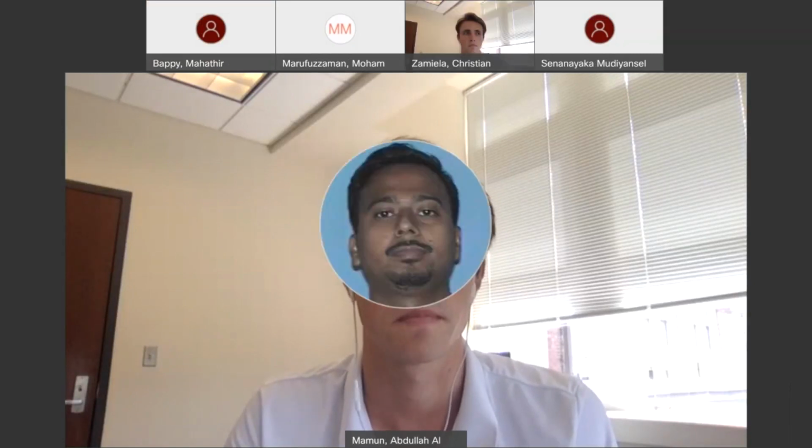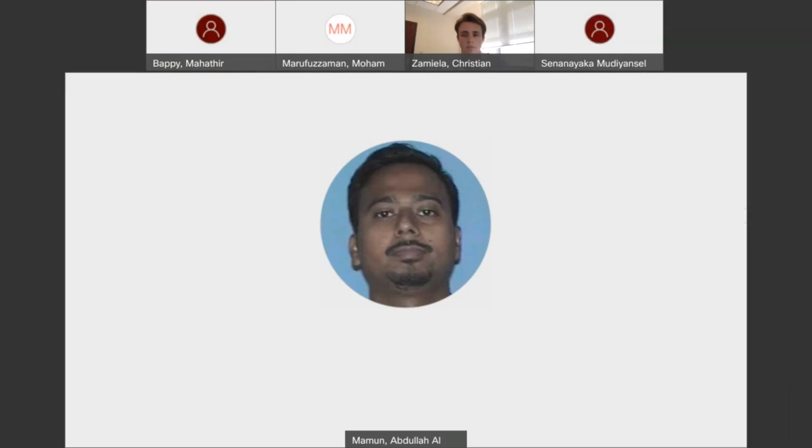Right. And then we classify those signals into different things, like one class versus the rest of the classes, so one versus all. For example, I can take my good bearing as class 0, and the other bearings are a mixture of different types of faults, so I can classify them as one class. Then we can train and test based on chunks of our data set in the artificial neural network, and test our accuracy, how well the machine can detect the fault class.